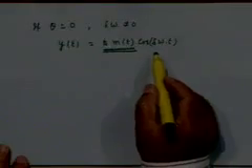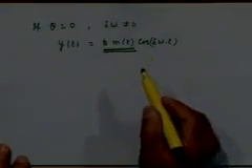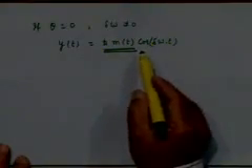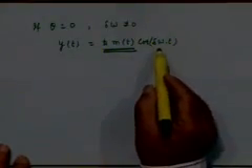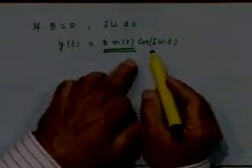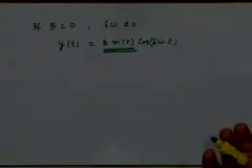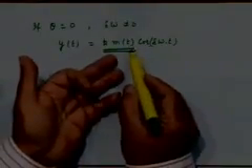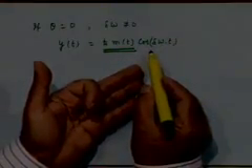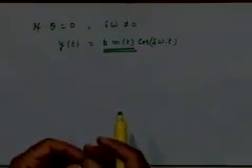Delta omega is okay. His doubt is if you pass this through another low pass filter, you will get m of t back. Please remember that this is a modulated signal again, but the modulating frequency is extremely small. Even if it has a high frequency, a low pass filter would not be able to remove it, because the whole thing is translating around that new frequency, right? So in fact the low pass filter in that case would remove everything, right?